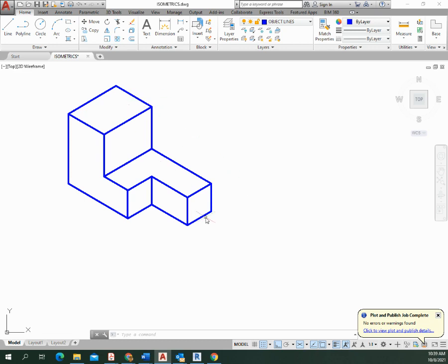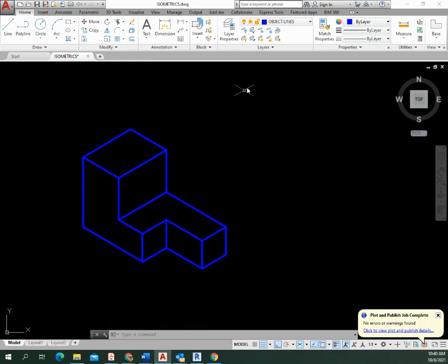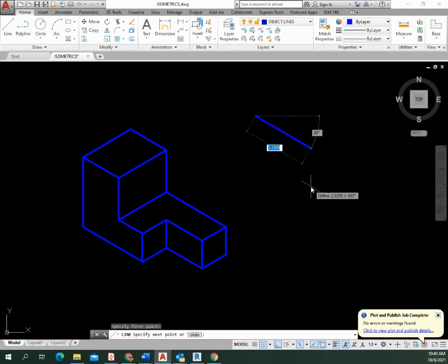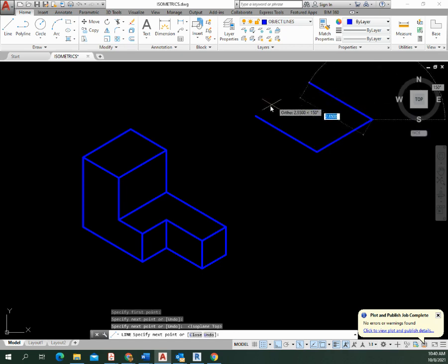I'm going to change my background colors so you can see it. All right, so I've changed my background color so you can see it. As you hit F5, you notice that the cursor goes in different directions. That gives you the ability, let's say, to go out to the right instead of up. I could hit F5 in order to do that. You can also use your tracking system if you want to close up a line, or you can just use measurements.